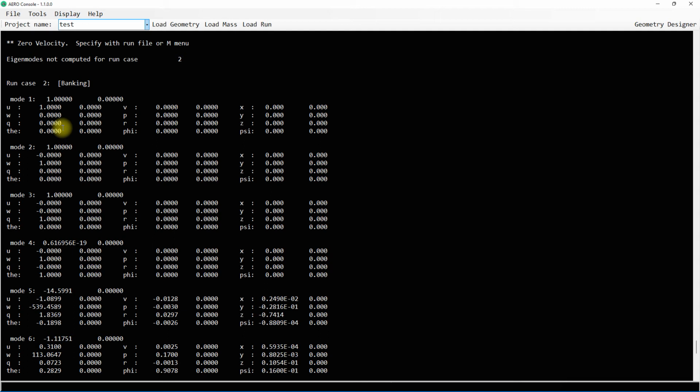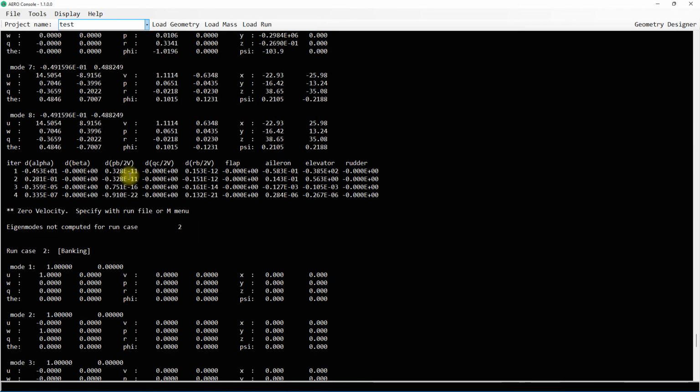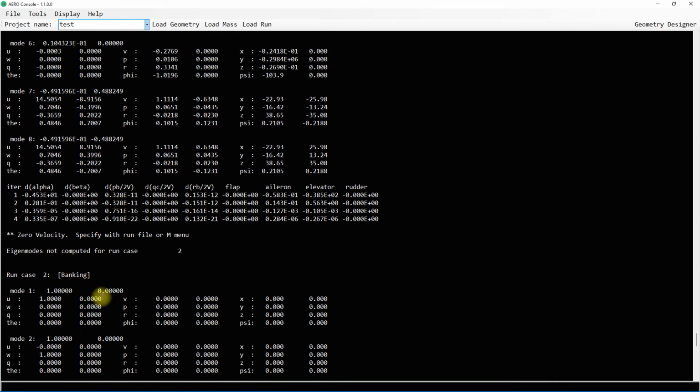For example, you can have the phugoid mode, and other modes related to the analysis of the dynamic stability of the aircraft. But in AVL, they are set up with numbers as mode 1 to 12. Technically, only 8 of these modes can be more relevant in general, but in reality, you do have the full 12 modes that you can analyze. We see that there is some information for each case.